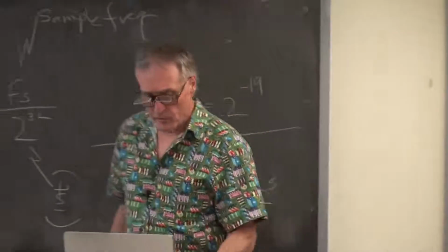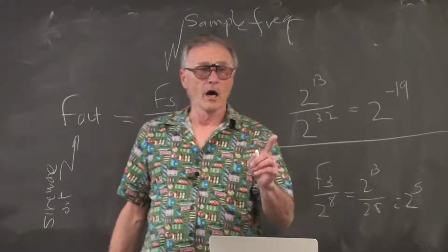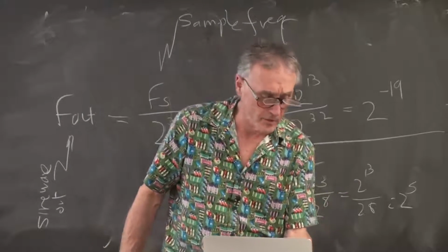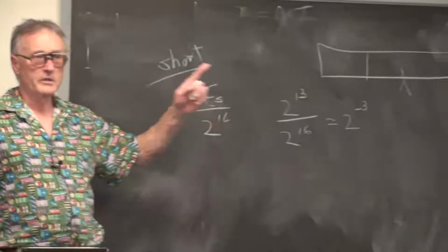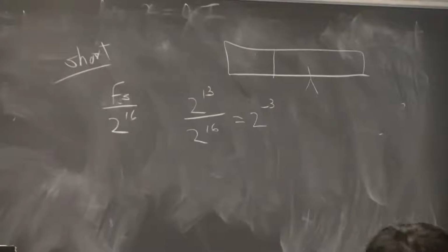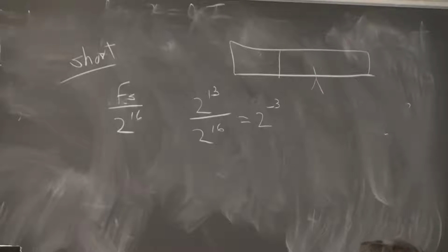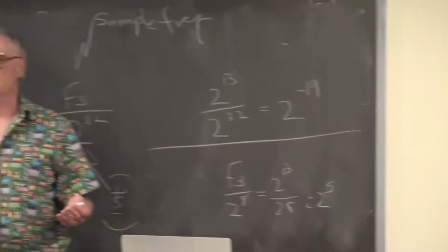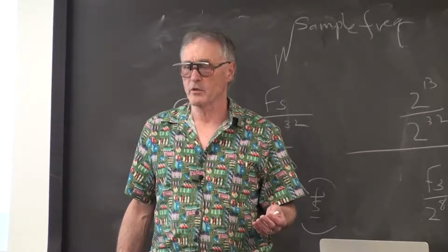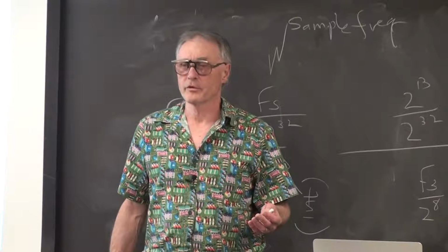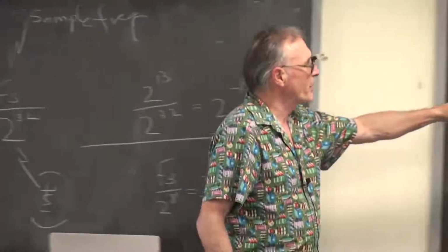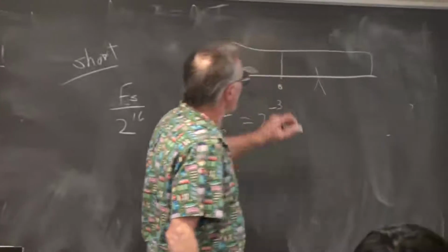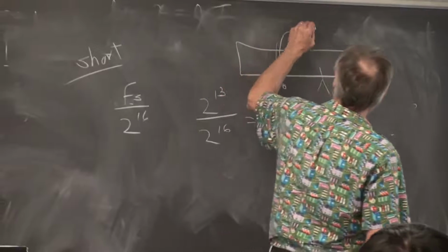I would never use floating point in an interrupt service routine because it cuts into the performance quite significantly. This requires an add and a shift, which is much faster than doing a floating point multiply. In this case, you could probably get away with it by lab 3. If you use floats to do the work on this processor, you won't be able to do the lab. So you may as well get used to fixed point. You can think of this as a fixed point number with the binary point right here, where this represents one index value.